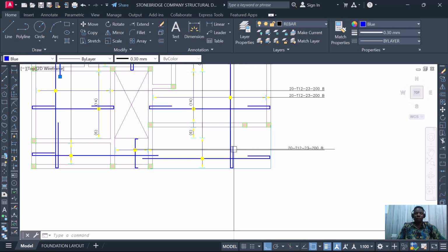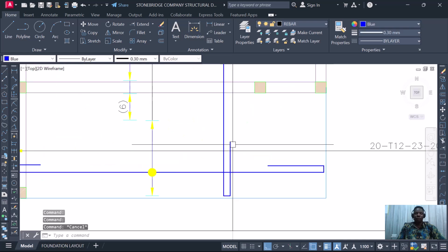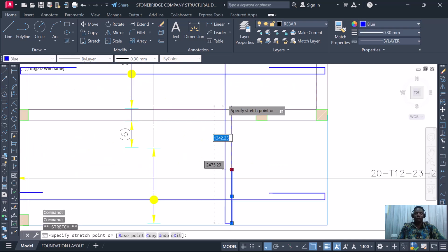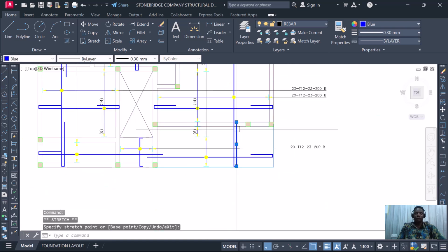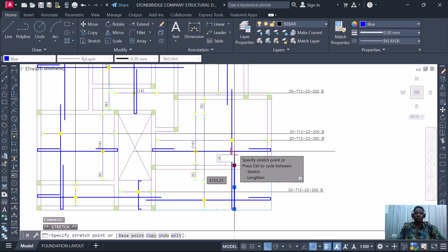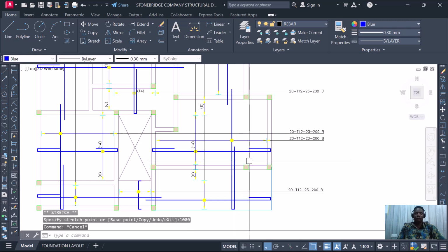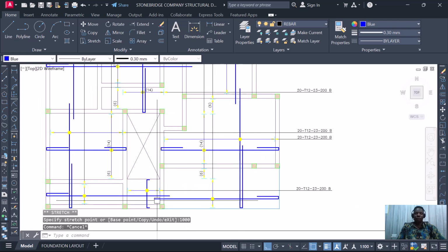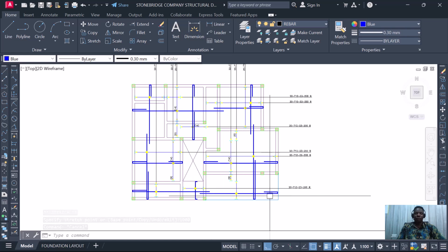When you get to the edge along that main axis, we have the distribution, like we said earlier, and we have the main rebar. The distribution line is the longer line. On the shorter span distance, we are going to take the reinforcement and return it down back to the beam. You can see what we did here: we take this reinforcement down and return it back to the beam. From the beam, we can now extend 1 meter. So this is how it is supposed to be.